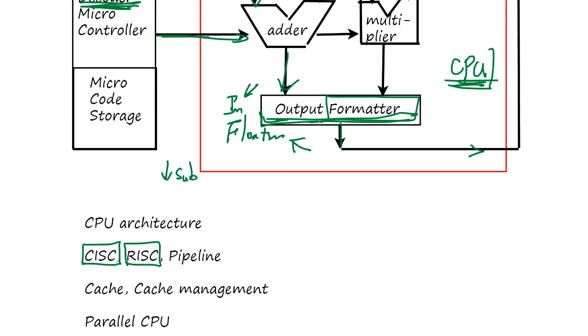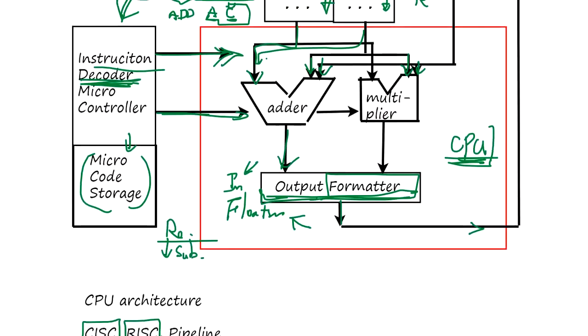The subtraction is repeated many times to get the result, and you can do that in software using RISC, or the chip has built-in microcode which does it, because the intermediate result never goes back to memory. It goes back to the registers, and subtracts again. The data circles around many times. That control is done by microcode, and this kind of CPU chip is called CISC.